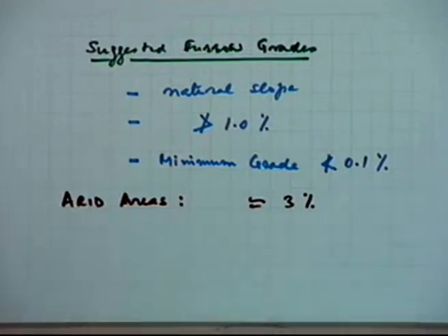The repercussions can be that the length of the furrow might be reduced drastically because there will be a lot of infiltration taking place at the upstream end of the furrow. So all those conditions govern what slope can be achieved, and it has to be looked at along with the other parameters of stream size and soil type.